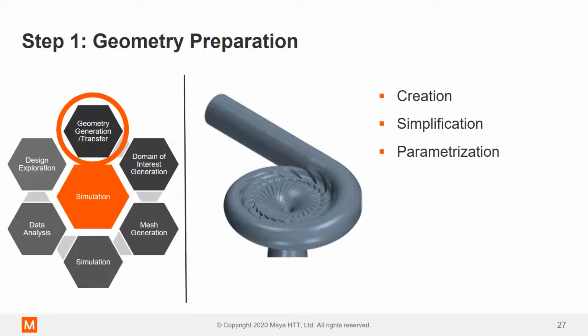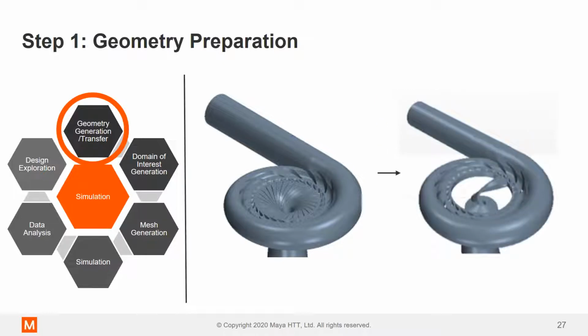For this given geometry, we're going to aim to simplify the geometry to contain one segment, using a mixing plane interface model for the full 3D geometry. So this is what we're going to achieve for simplifying the model, using a mixing plane interface for this segment in the runner, so as not to model the entire region.